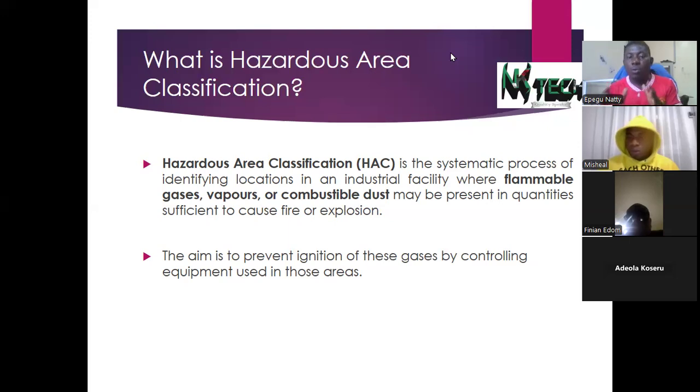So, in summary, hazardous area classification is a study that enables you to locate these gases, to map out the areas where these gases are available, and also position equipment that will be able to prevent explosion. You understand?